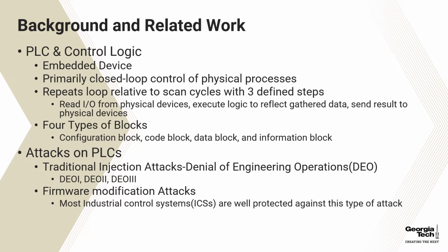Firmware modification attacks, on the other hand, are not a typical attack approach in the real world due to the protections that usually prevent unauthorized firmware modification or only allow direct USB or SD card connection for changes. However, if this attack is made, it alters the firmware, which then prevents proper communication between the devices and hence makes it harder to detect with engineering software, as it does not actually alter the control logic.